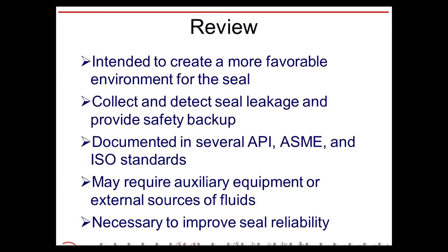So, again, to review, why do you use flush plans? Okay, again, intended to create more favorable environments for the seal, collect and detect leakage. They are documented API, ASME, ISO standard codes. You may require auxiliary equipment to run external source fluids, and these are imperative and necessary to improve the seal reliability.